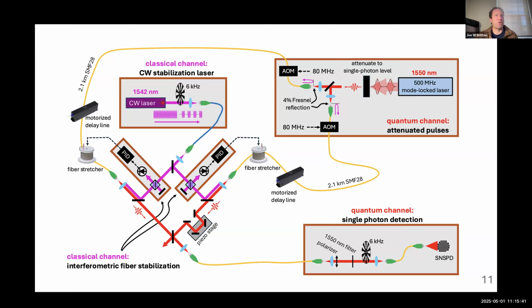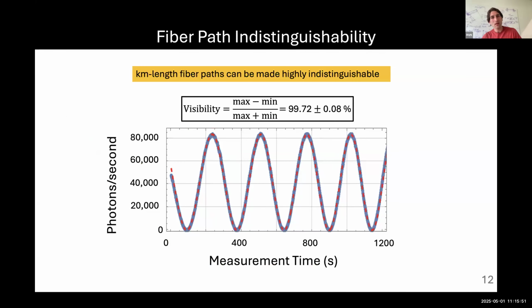So I have one other quick question. You showed this really nice interference on slide 12. Yeah, okay. About polarization stabilization. And so a question in my mind is, you are controlling the path length of the fiber, but for what polarization state? If you were to send in a different polarization, you'd find that the propagation delay is now different. And so you'd have stabilized it at one polarization, but not the other.